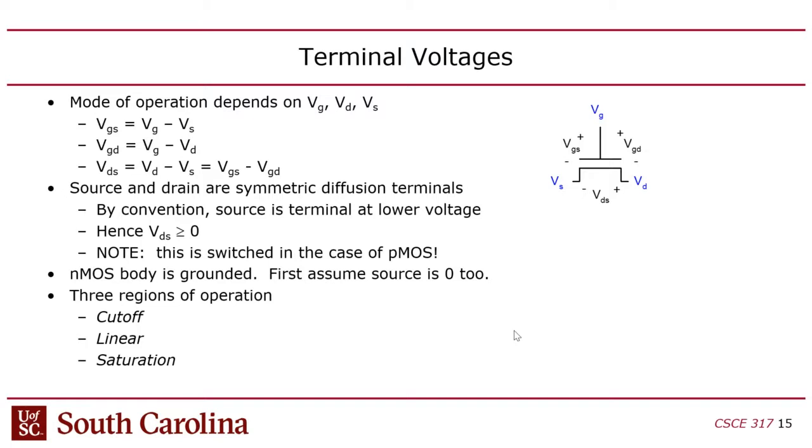However, once the voltage difference between the source and drain grows high enough, then you enter saturation mode, and the transistor stops acting like a resistor, because the amount of current that goes through the transistor will stop growing as you increase the voltage potential between the source and drain.